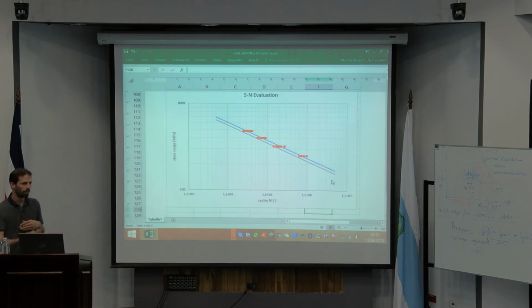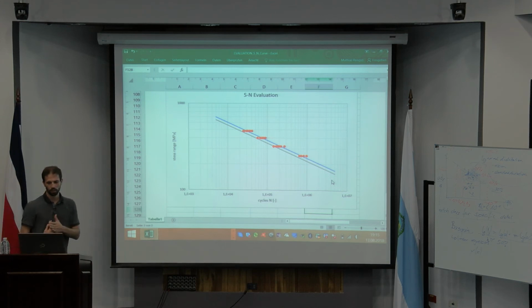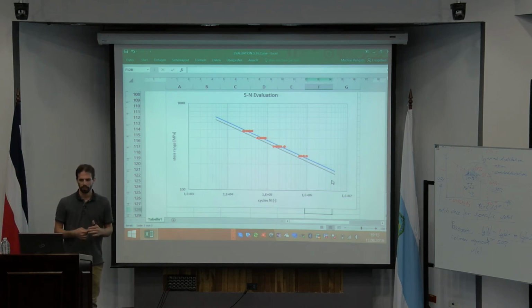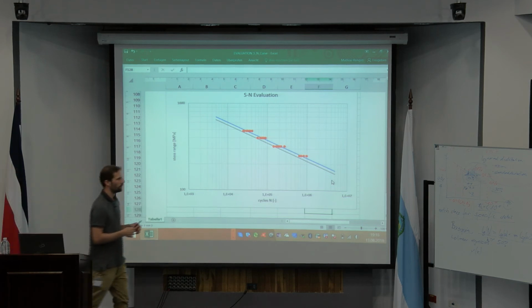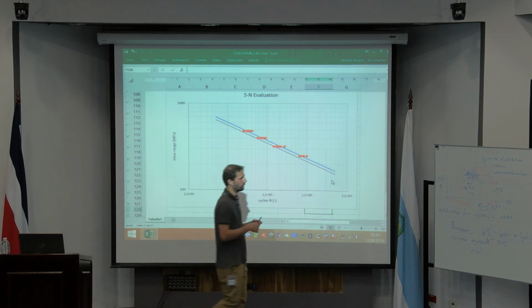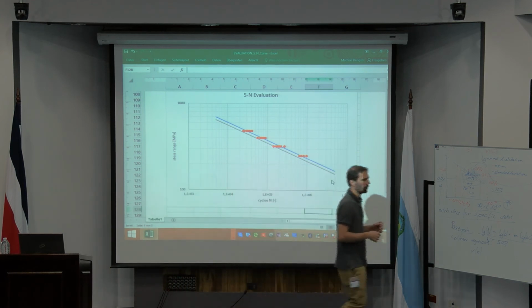And at the end, you have to recalculate it to the stress ratio of 0.5, which is related to the codes. And then you would end up for a notch detail of 160, which also fits to the tested material, which was here.